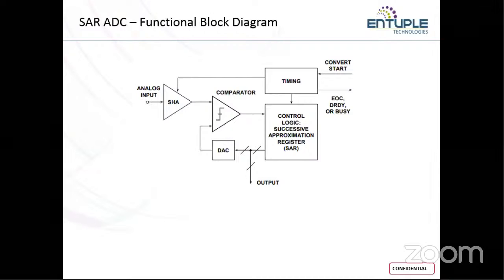That is taken as the input by the successive approximation register, and based on that it generates a digital data and translates that digital data to a DAC.